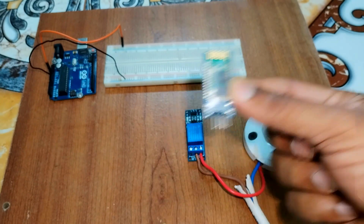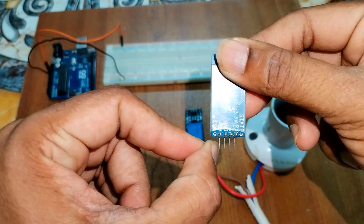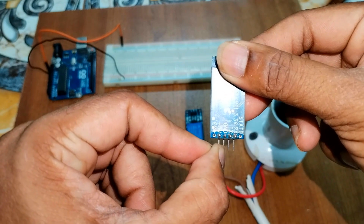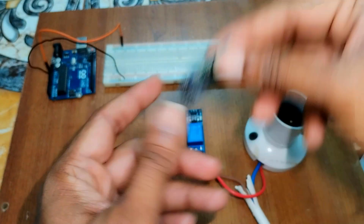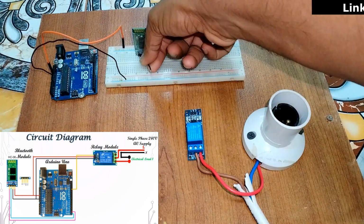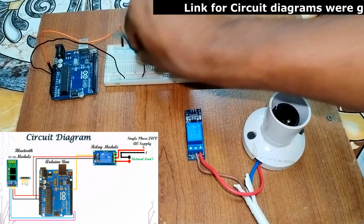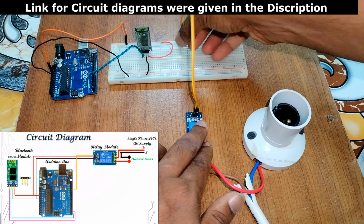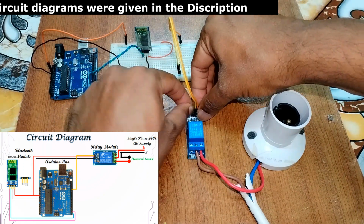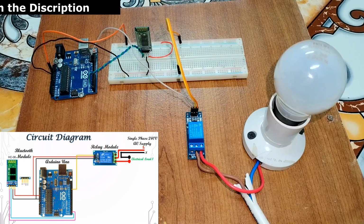This is the Bluetooth module. Now we are going to control this electric lamp using this Bluetooth module. So in the Bluetooth module, this is the VCC pin, ground, transmission pin and receiving pin. You have to connect it accordingly. So the connections are finished. Now we will see about the Arduino coding for this.